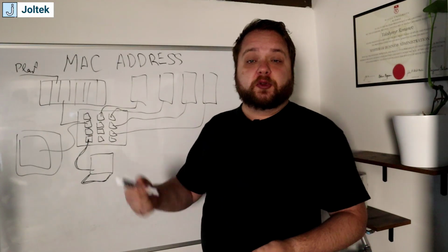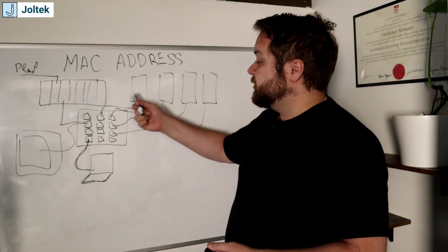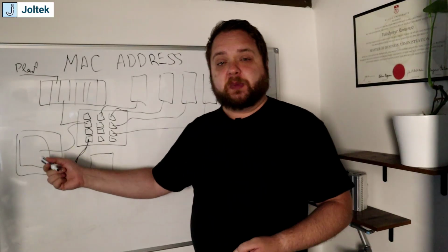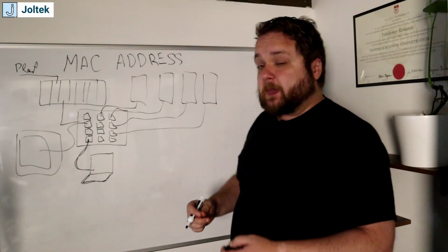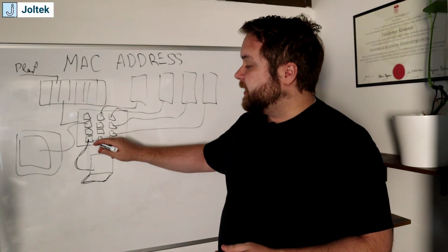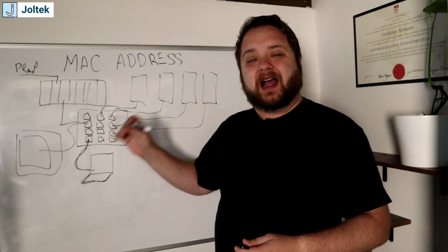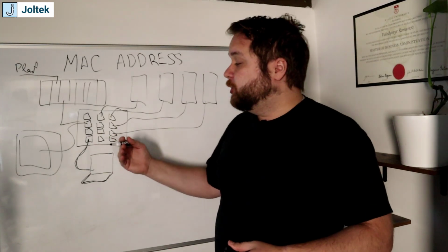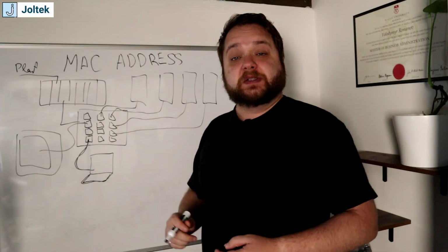You can scan the entire network. You can use a tool on the Rockwell side called BootP. You can use Connected Components Workbench for your VFDs. You can use some other tools like RSLinx, for example, for some of your HMIs. But the challenge here is as follows. As you connect to a system that has multiple devices, whether they have IP addresses or not, you will immediately be unable to identify which device is which, right?